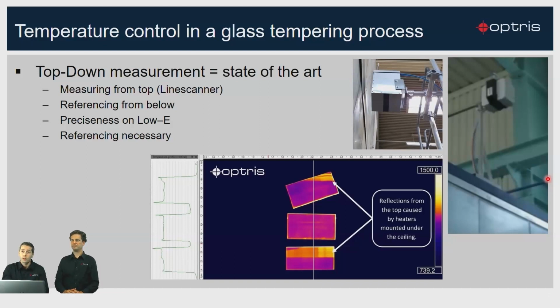And even worse, this is acting like a mirror. In this case, you can see there are some reflections from the top, from the heaters that are in the facility. So the temperature at this point is just not valid. So you need to reference actually from the downside.